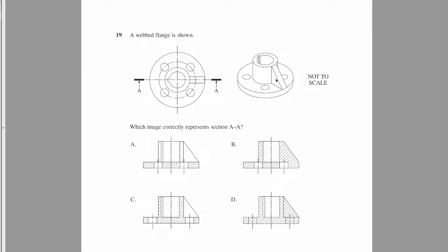It expects you to show 2 stiffeners and 2 holes in the section. Okay, so that's why these holes are shown here and not close. So if we look at this picture here, we can see the hole should actually be down here, but we've rotated them to be on the sides. The reason we've rotated them to be on the sides is because we're using a pitch circle diameter. So that's why we're showing the holes running through.